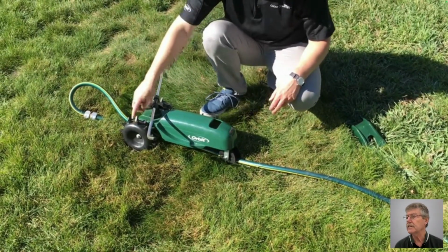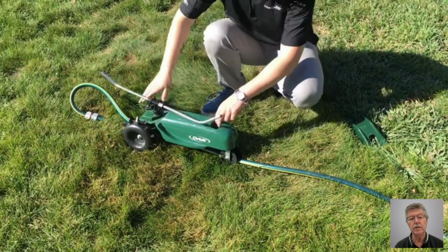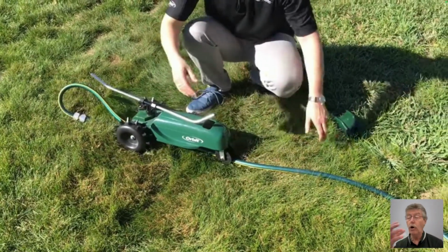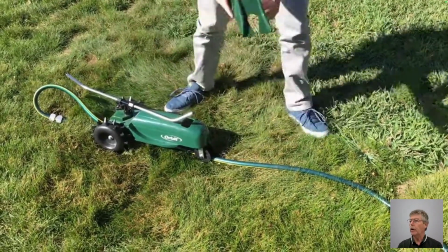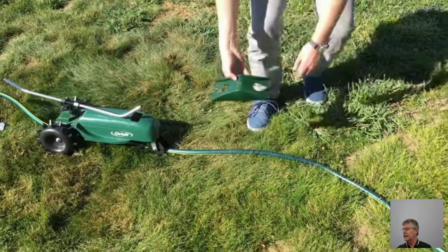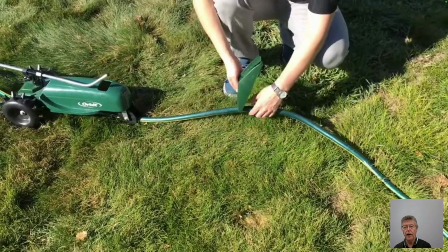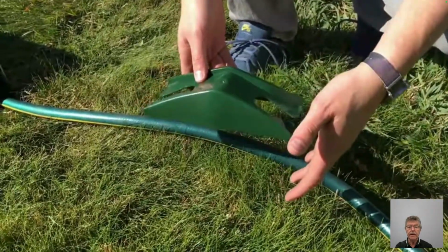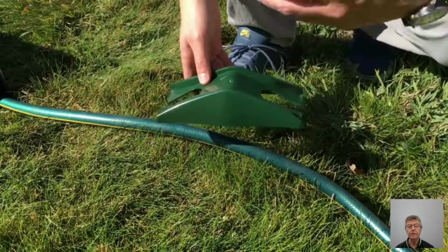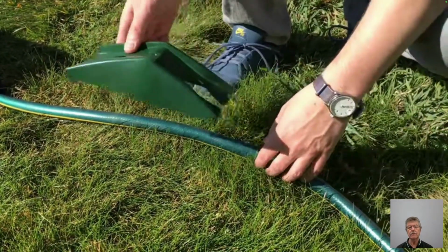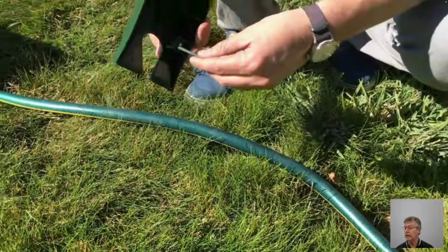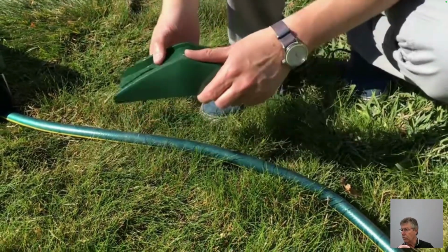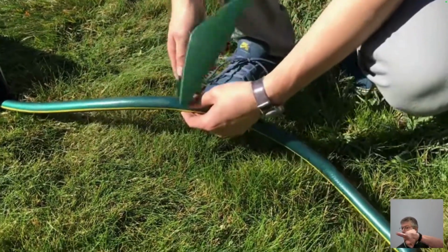And so that's the problem that we'll look at today, to be able to see what controls the velocity that head will go at, what happens if you hold the shaft static. And probably you could imagine that if you hold it static, that will be the maximum force you have to apply to get it to stay static, and the velocity coming out of it will travel the furthest. And if you allow it to rotate, the limiting rotation speed would be where the water is exactly coming out of the jet, and that bead of water would just drop to the floor immediately because of the velocity that the rotor is going at.